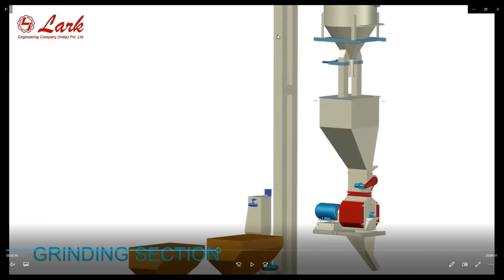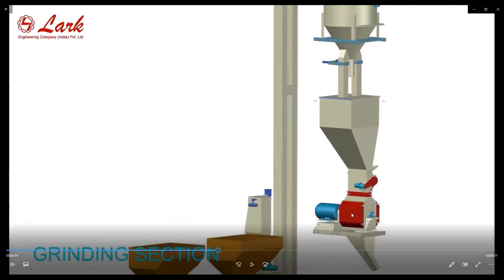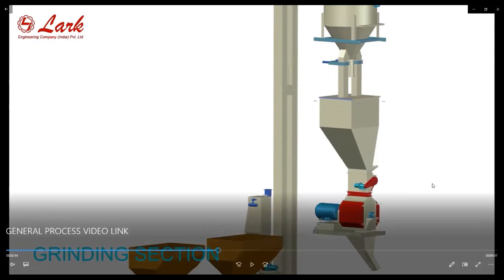One more advantage the rotary vane feeder offers: when there is a power failure, all the material in the buffer hopper goes to the hammer mill chamber, blocks the screen, and jams the complete hammer mill. So this rotary vane feeder cuts the material in case of power failure to avoid the leakage and the jamming of the hammer mill. So that is the purpose of the rotary vane feeder above the hammer mill.